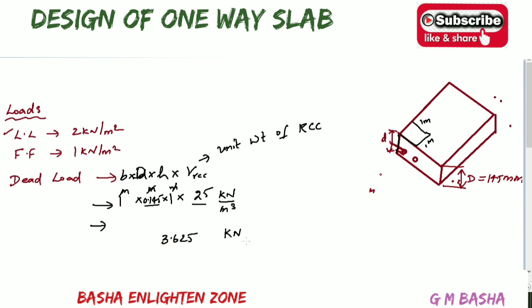in terms of kilonewton. But here we are calculating this entire dead load for 1 by 1 meter, meter square. Therefore we are considering kilonewton per meter square. If you observe here, you will get that point very clearly. Live load will be given in kilonewton per meter square, floor finish will be given in kilonewton per meter square.